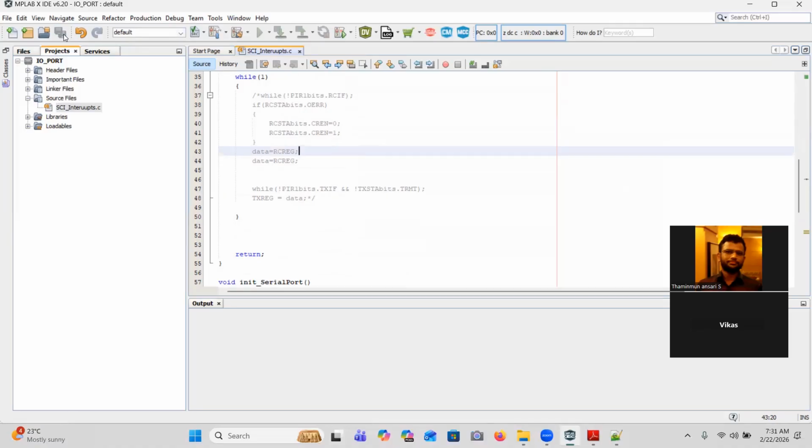the data. So as far as the microcontroller is concerned, when we put this data to the TX register, automatically it will transfer to TSR. From there it will go out. Monitoring TXIF will not make any sense to us, because that only helps to know that the data has been transferred to TSR. That's all.